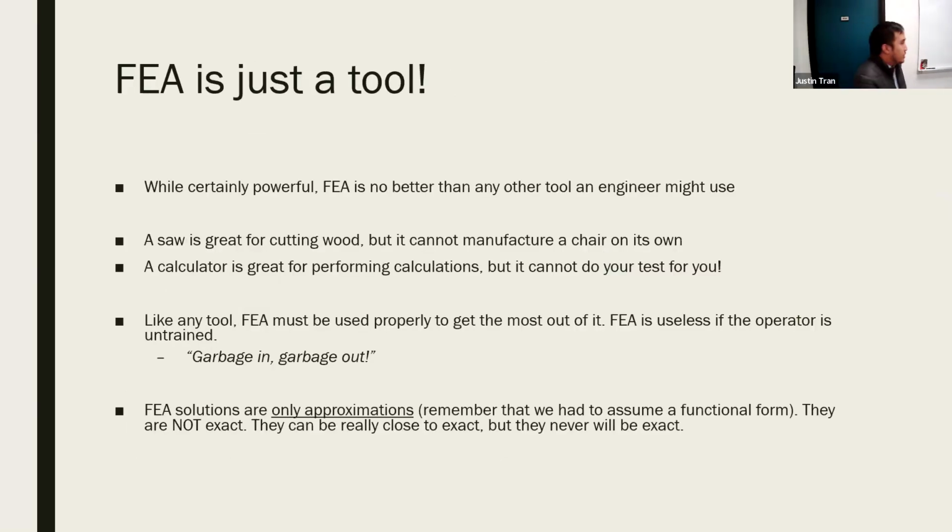Okay. And then this kind of just says the same thing. And in fact, among people that do FEA, there's a very common phrase that's thrown around, which is called garbage in, garbage out. What that basically means is that if you put garbage into your simulation, you're going to get garbage out. If you don't set up your simulation properly, your mesh is not well refined, your boundary conditions are incorrect, maybe you're using a wrong material property, you're going to get an incorrect result.